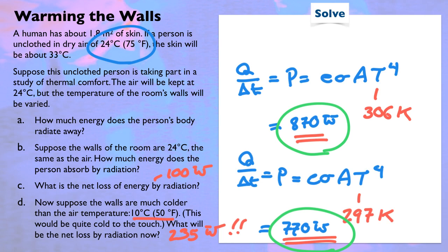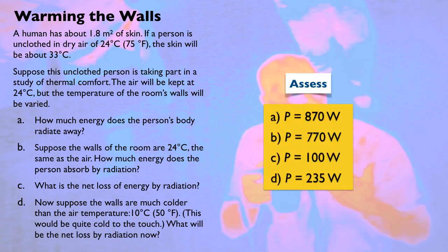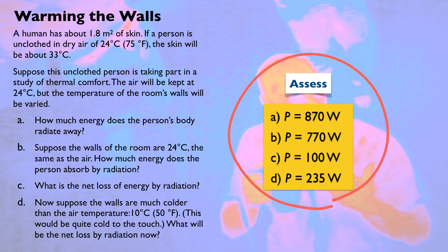And that was one of the things they discovered in these studies of thermal comfort. More important than the air temperature was the temperature of your walls. Right now, I am doing this in a room with a lot of windows and I've got some French doors. I would guess that a quarter of the wall surface surrounding me is not walls, but it's glass. And the glass is a really good thermal conductor. It's very, very chilly. And even though the air temperature in this room is the same as in other rooms of the house, I feel chillier here because I'm radiating energy outward and I'm just not getting the love back. And so the temperature of the walls is very, very important. My assessment is this is kind of crazy. These numbers seem amazing, but that, in fact, is how the world works. And when you do future calculations, you'll be able to use this as a benchmark for comparison.